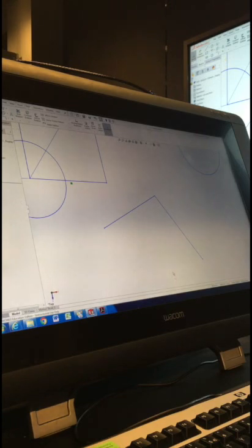Right. The same way that you delete relations, you can also add them. So if I've got a line that I want to make a vertical line, I can select it, and when you select any sort of sketch segment, on the left of the screen you can see properties, and if you go down, there's an option there to add relations. So I can add a vertical relation to that line, okay, and it's going to make it vertical. All right, makes sense so far?